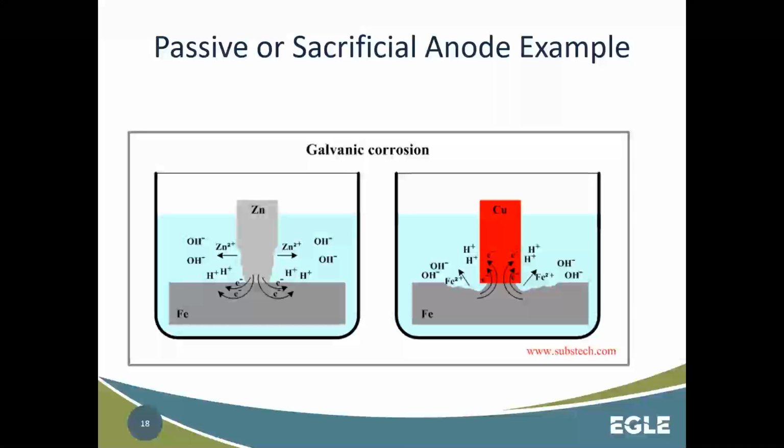All right. And this is exactly what we're talking about here. Imagine this is a hot water tank. You have this solid iron chunk nearby this zinc, which is higher on that activity scale. So it's more likely to drive off those electrons, protecting that iron, losing the zinc.